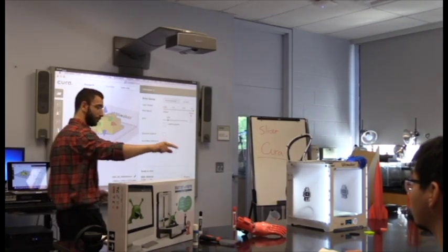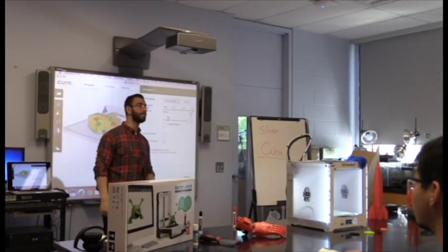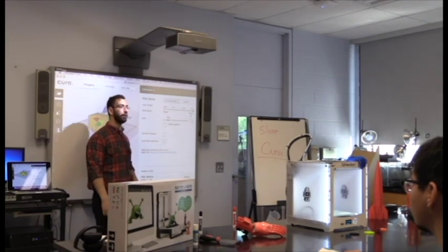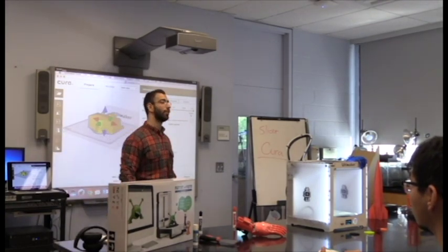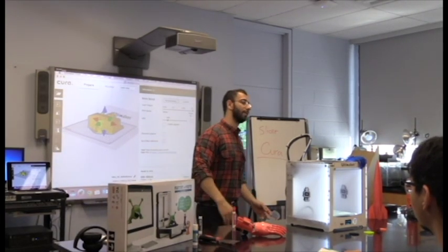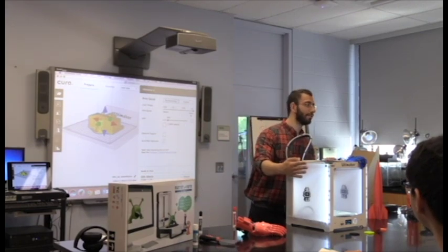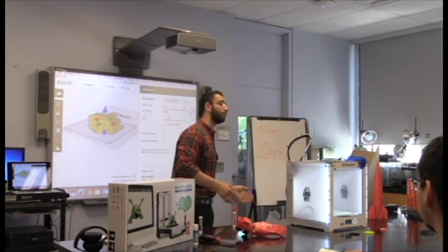Yes, you can. In this printer, you can go all the way down to 50 microns, so 0.05 millimeters. That takes super long, but you get beautiful prints. Some printers can't handle that. Usually cheaper printers can handle it down to 100 microns, so 0.1 millimeters.